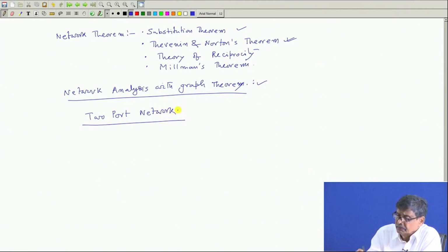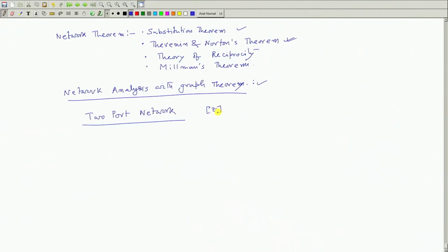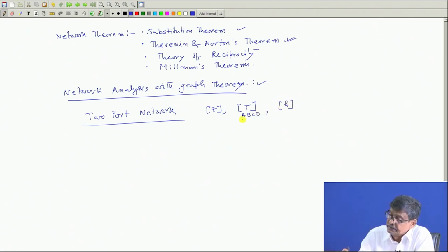And here also several lectures I have taken to find several representations of two-port networks, what a two-port network is, and impedance representation, Z matrix, then T matrix, which is nothing but ABCD matrix, then H matrix representation, and the inversion of Z is Y matrix, ABCD inversion, no name is given, I think, H parameters, its inversion matrix is G matrix, conductance matrix, and so on.